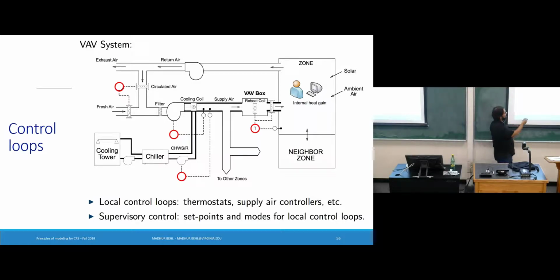The same thing actually happens with the air handler unit. Okay, so the air handler unit has to send air at 55. It can do so with two mechanisms, by adjusting the rate at which it is pushing the air across the cooling coils, and also adjusting how much the flow of the chilled water occurs in this heat exchanger. So again, there is another PID over here, which is looking at maybe the air is at 57 degrees Fahrenheit, but the desired supply air should be at 55. So it will open a valve so that more chilled water can flow through the heat exchanger, or it will start blowing the air faster across the heat exchanger. Again, a local PID.